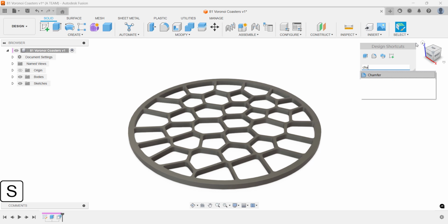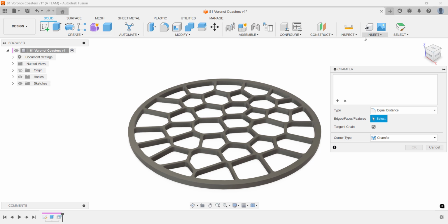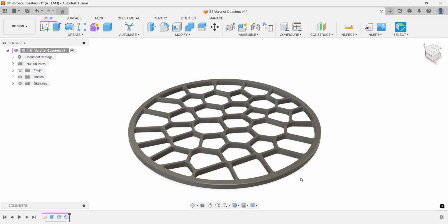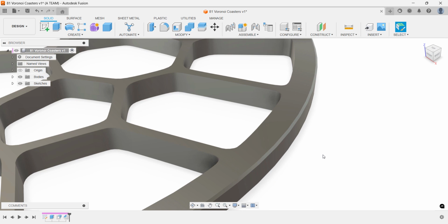We're almost done in Fusion, but before we wrap up, let's add a few final touches to the 3D model we built from the initial sketch generated with ChatGPT. A chamfer is easy to 3D print and adds both elegance and strength. While 1 mm is a bit too much for a design this thin, 0.25 mm looks just right.